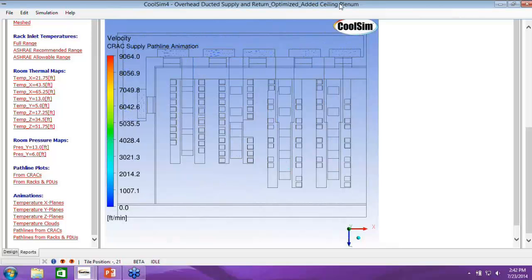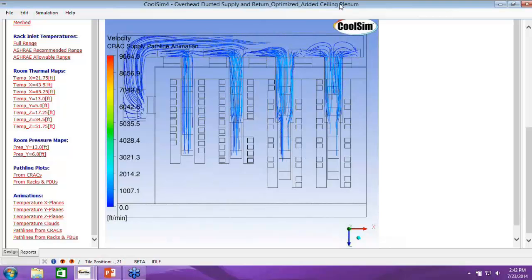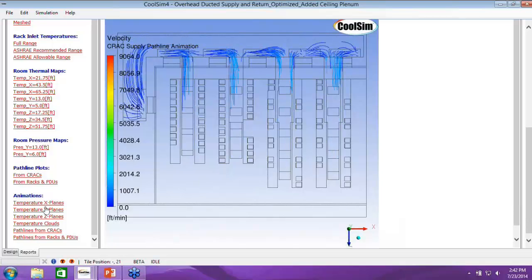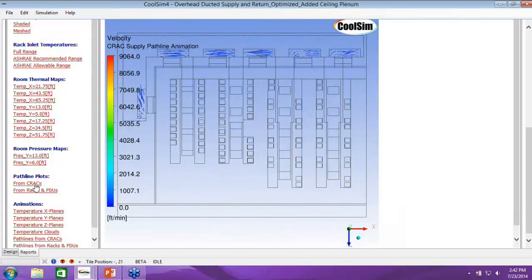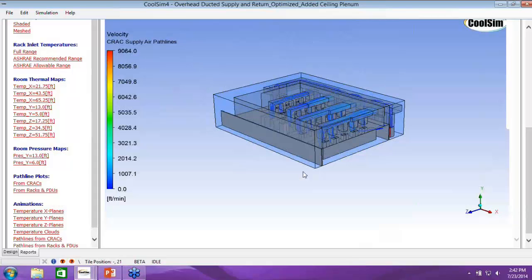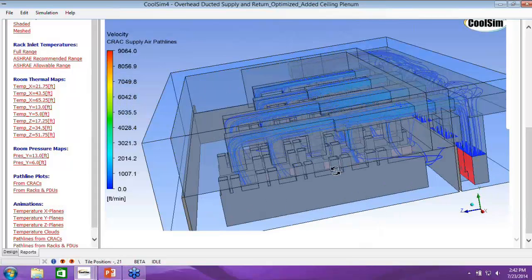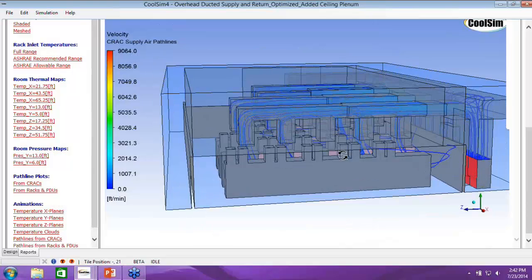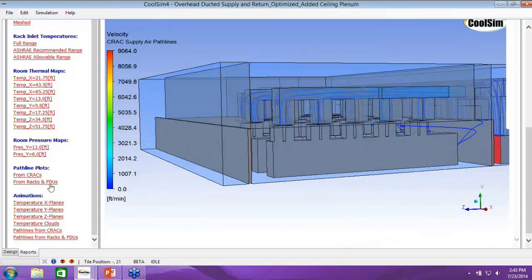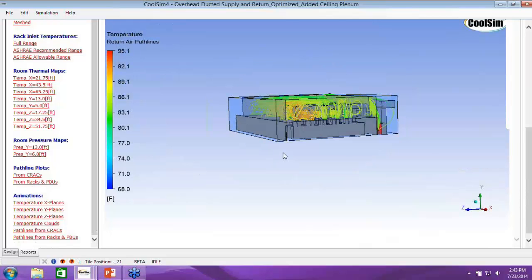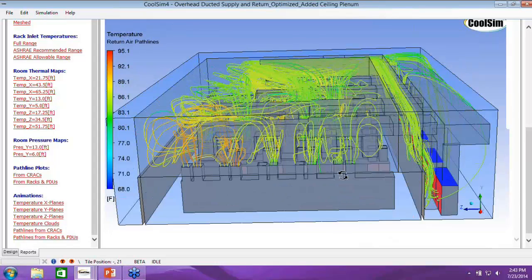Okay. So Paul, I'm going to put you on the spot here now. This methodology you have, that first you're fixing the airflow rate, and then you're looking at the RCI to crank up the supply temperature as much as possible. I would love to see that this process could be automated in one fashion or another. So you first put in the data you have now, and then the system steps through the same process as you do manually now, and it stops when all of the metrics are close to 100%. Yes, you're absolutely right, Magnus, and I agree with you.